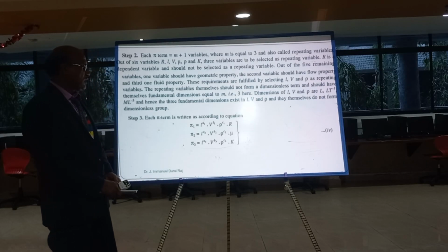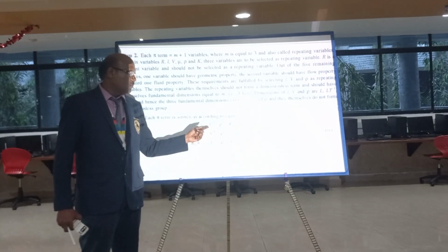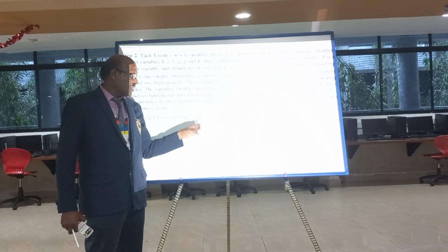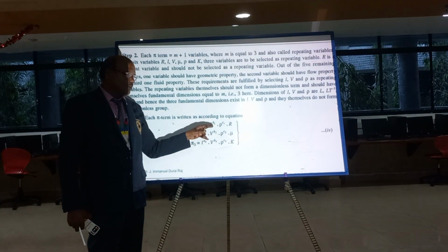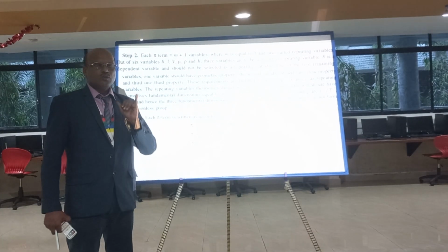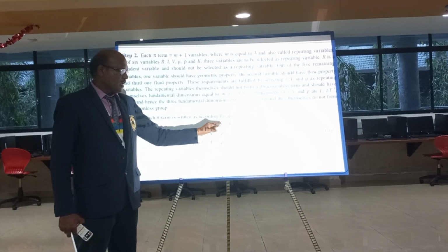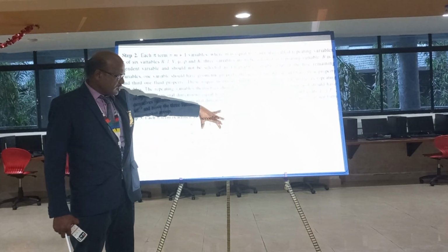So find out the repeating variables. Normally you will choose L, V, rho, and in your problem they are available, so I am choosing L, V, rho. The repeating variables should contain geometry, flow and fluid. Select these 3 as common terms.